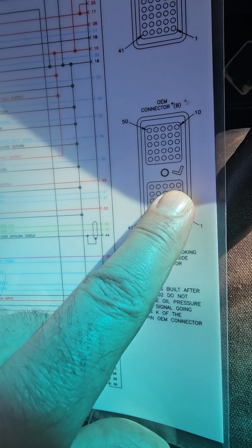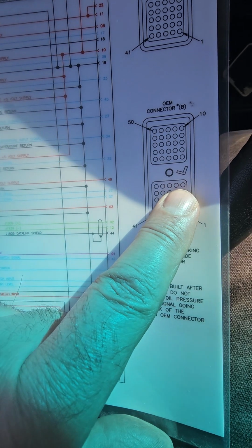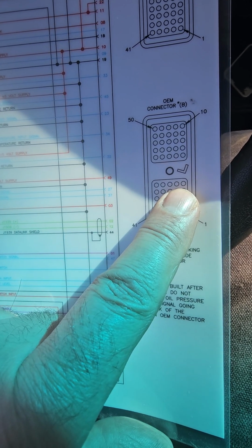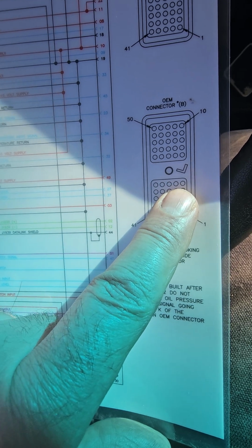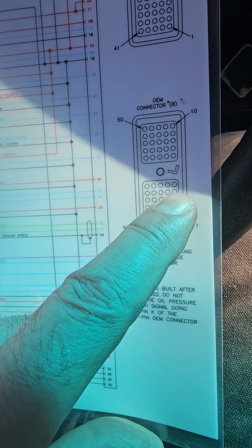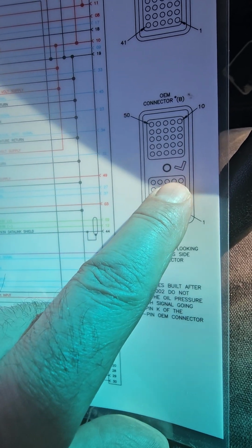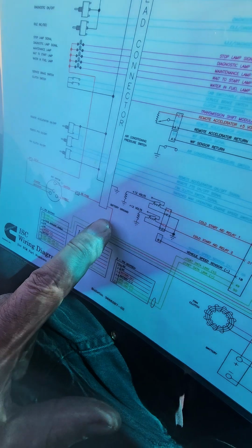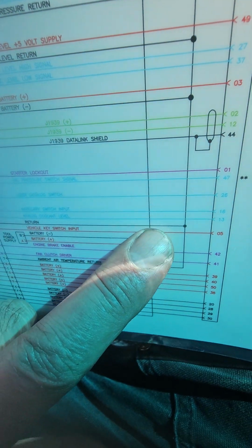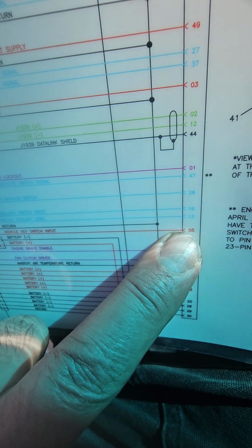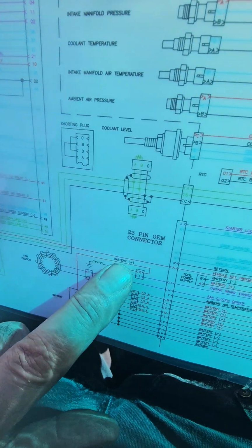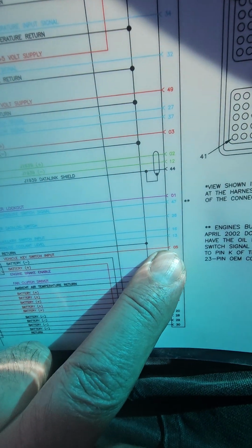And I tested position 5, which was ignition voltage, and that guy was a little bit more than 3/4 of a volt less. So it doesn't sound like a big deal, but usually what that means is it's not only 3/4 of a volt less, but the actual line, this line right here, is carrying a load like a light bulb filament. It's actually creating a voltage drop, and there shouldn't be a voltage drop in the actual electrical line. There shouldn't be resistance there.